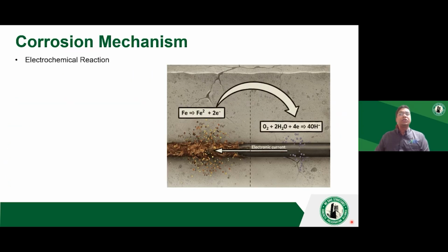In context of corrosion of steel, corrosion itself is an electrochemical reaction, meaning electro is the electronic part where you're talking about transfer of electrons through a metallic conductor, which can be a rebar. And the chemical portion of the electrochemical reaction is transfer of ions that happens through the electrolyte. In this case, concrete can be an electrolyte. It can also be soil or water.